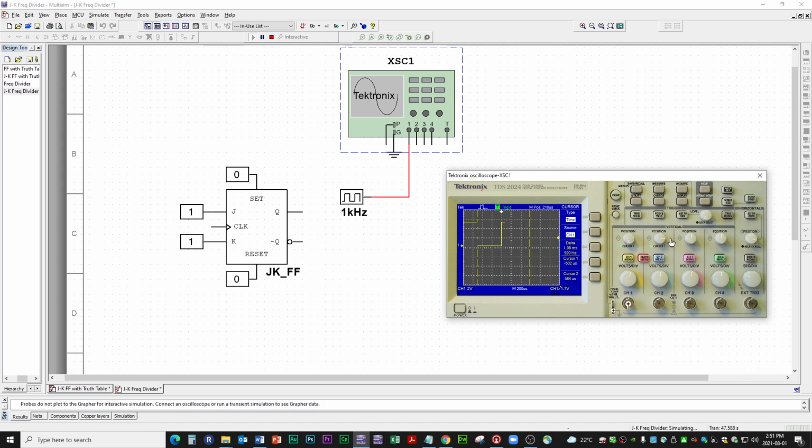Let's bring that cursor right there. All right, there we go. And what does it show? It shows 994 because I wasn't able to get this exactly to this point. Can we do that? There we go. We're aligned with this point and with this point, and this shows the timing reference from 0, cursor 1, cursor 2, and the difference between those cursors in timing gives us the calculation of 1 kilohertz.